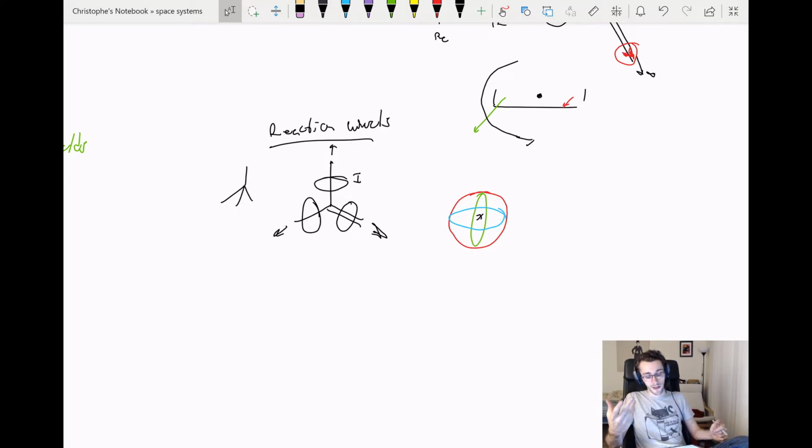One thing that you can do is desaturate your reaction wheels. That means you can slow down that reaction wheel and then compensate that angular velocity with another system or another reaction wheel, or in this case, if you're in a tetrahedral orientation, another pair of reaction wheels.